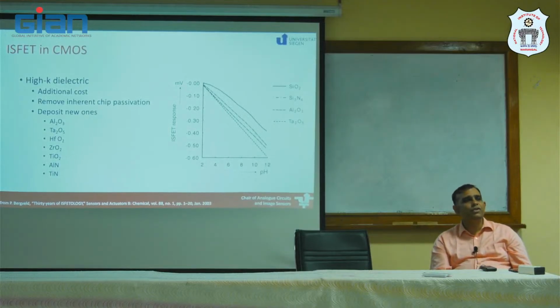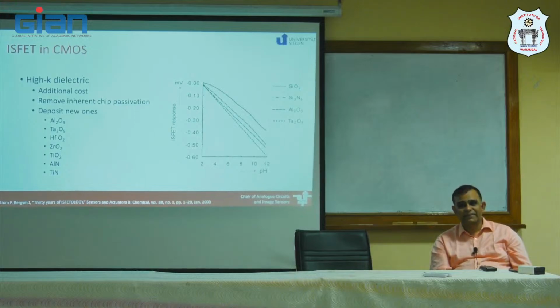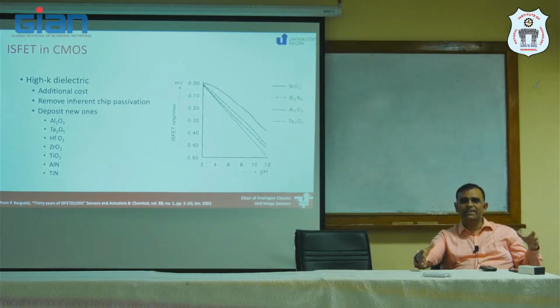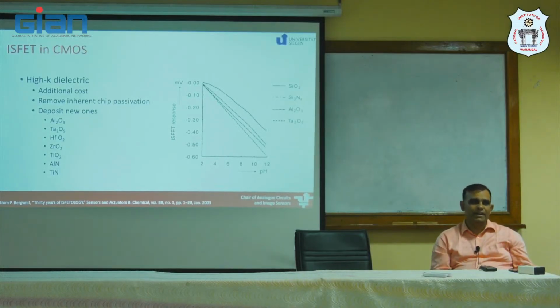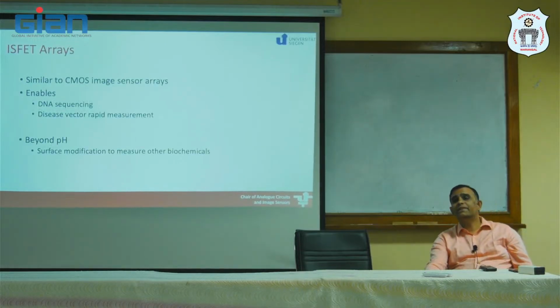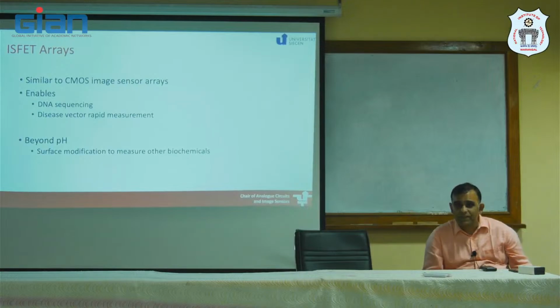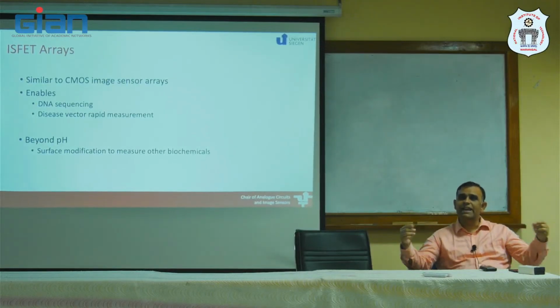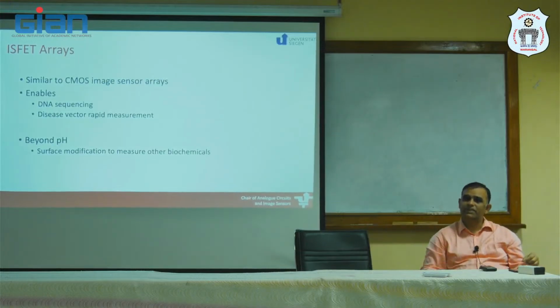Now, till now we talked about a single ISFET, a single pH sensor. Ideally, we would like to measure pH in an array, to see how things are happening in a square or rectangular area. Now, life again is not very different from what we did in the image sensor world. We have got individual sensors. We create a 2D camera-like design for these individual sensors.